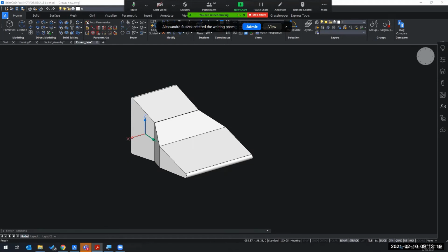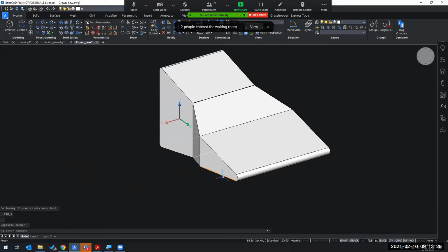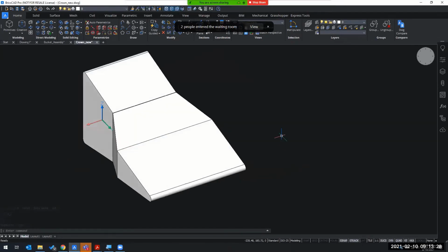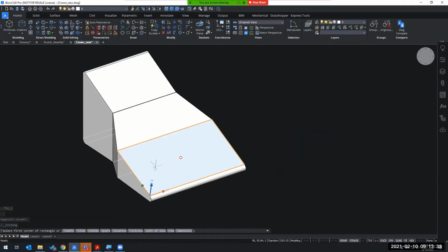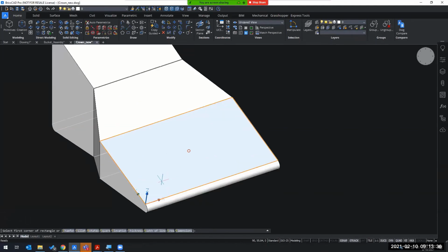So now that we have that, how about we add a protrusion feature on top of this crown? So how are we going to do that? Let's go ahead and draw just a 2D rectangle on top of this face. For those of you who are not familiar, you can see that the UCS adjusts temporarily. If I hover out of that face, now my UCS is world UCS. If I come here, it's going to change. And also what I can do is lock it, so I know it's not going to change last minute. And second, let's say you have to draw somewhere else, you can.